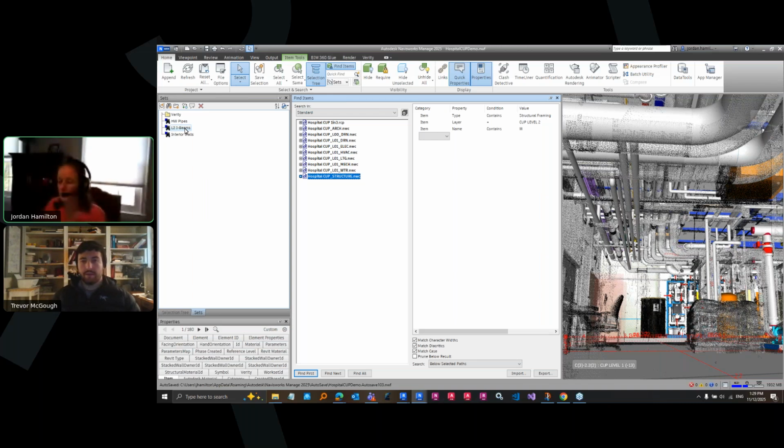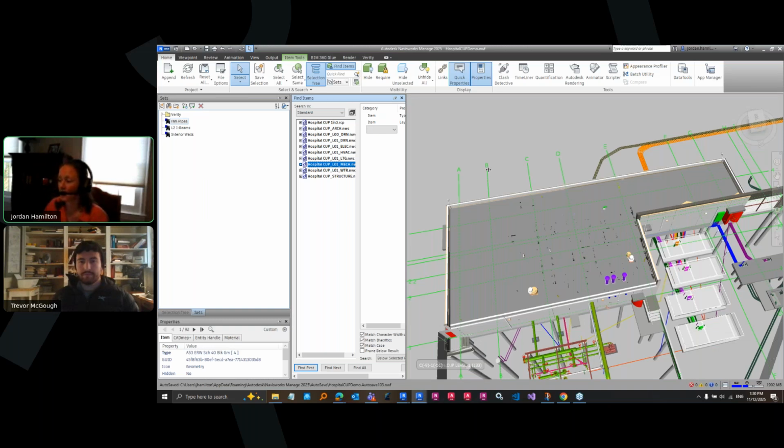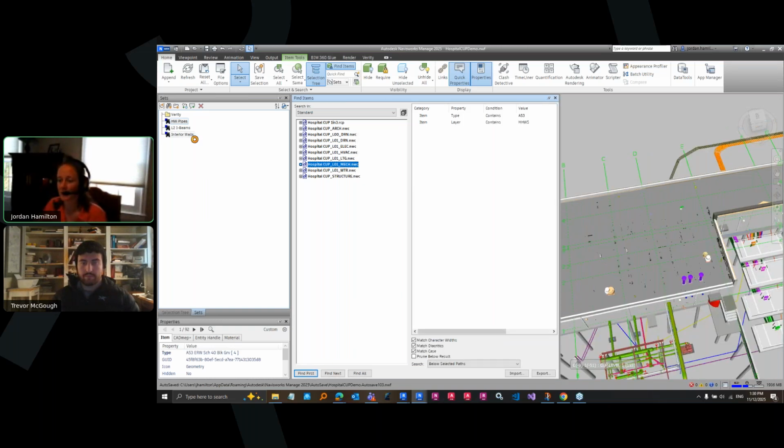You can do a similar search set here based on item types that are matching your pipe names, and the layer matches the hot water layer to ensure that those are the correct pipe types that I need to take a look at. Same thing for walls. A lot of these walls in this model have both an exterior portion, a core portion, and an interior portion.